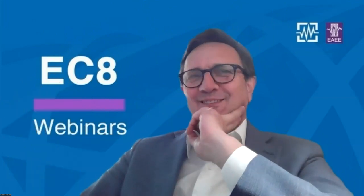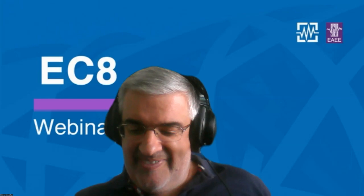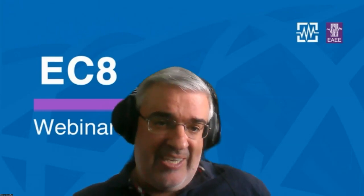Oh yes, it's true. And the more elastic your components are, and the less elastic your structure is, and the heavier those components are, the more important this becomes. And actually, there are no rules to tell you. There are some recommendations, seen in the American code, that say 25% of the max mass of the structure is allowable for a component to be interacting, which is actually quite a lot.